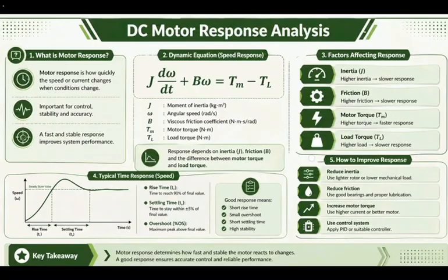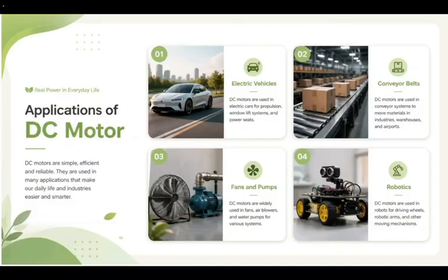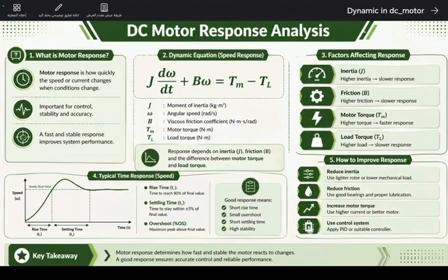Factors affecting response: inertia, friction, motor torque, load torque. How to improve response: reduce inertia, reduce friction, increase motor torque, and use a control system.